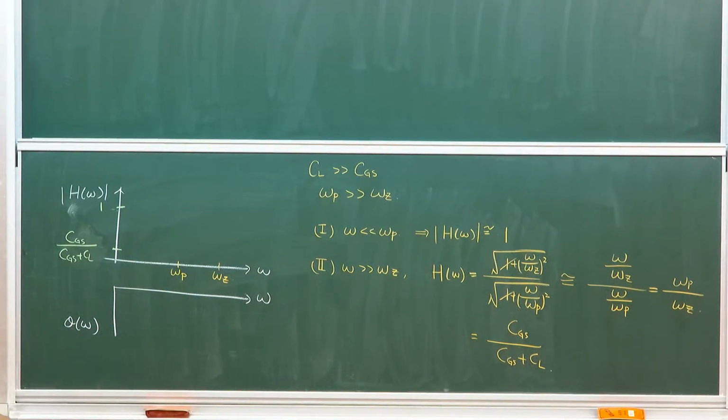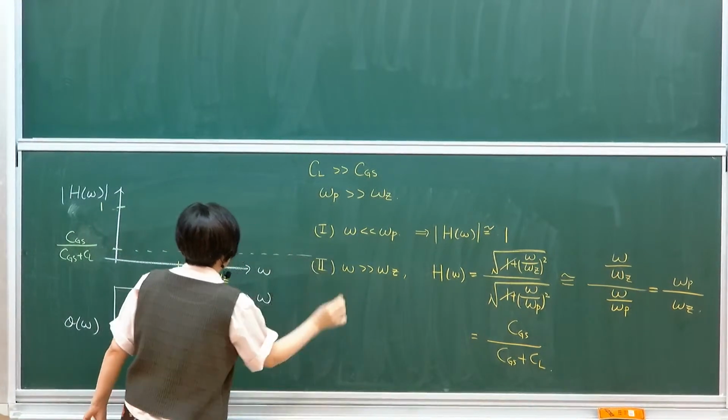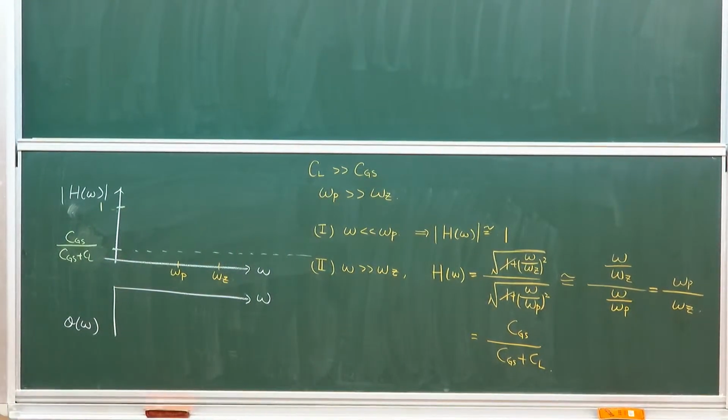So I know that at a very high frequency, this is where it should return to. And at very low frequency, you actually have a perfect source follower. It's an ideal source follower. Your loading impedance is infinite. That means that you have an ideal gain, which is at 1.